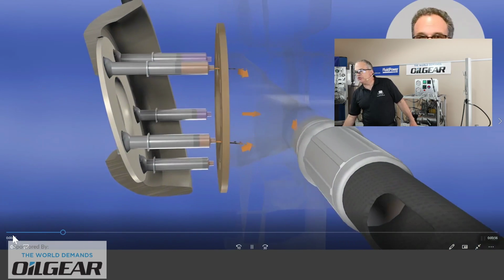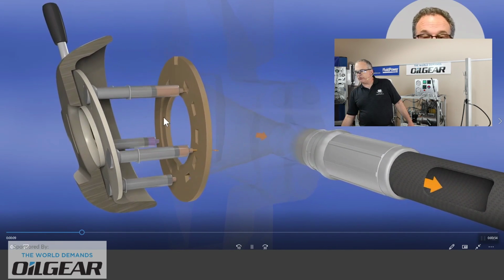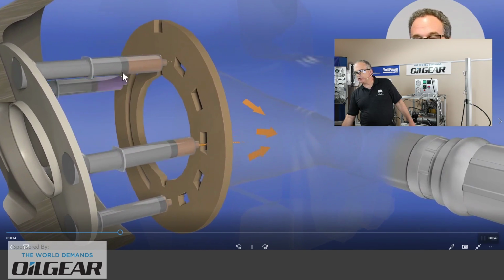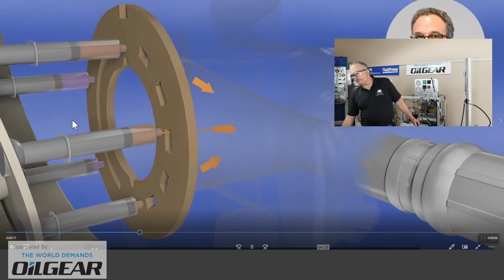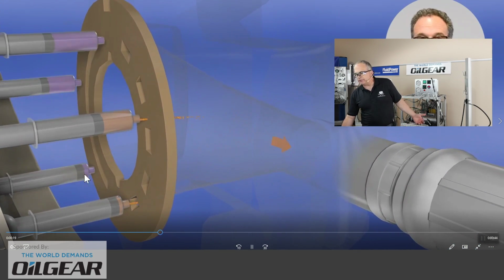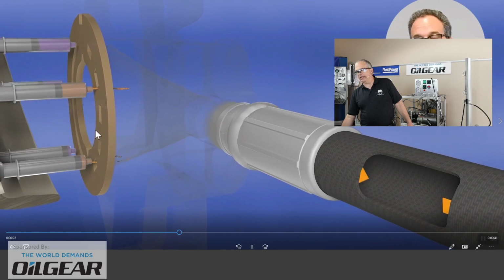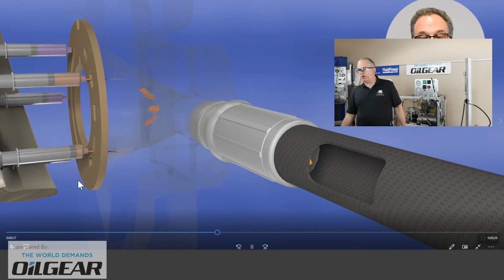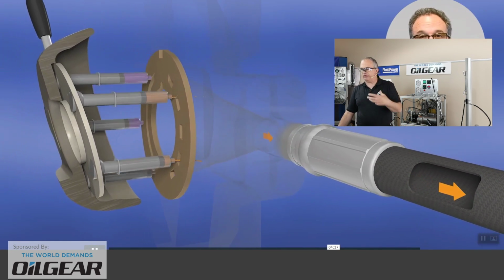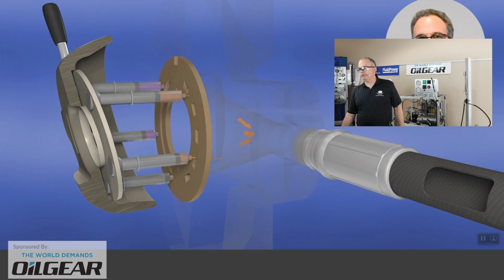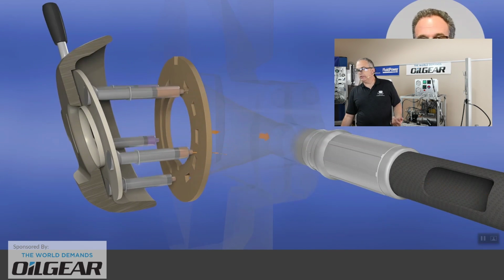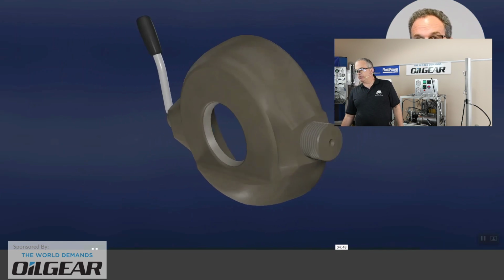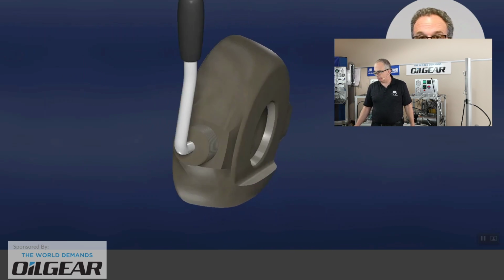And you can see those syringes drawing back on the inlet side, drawing in oil through the larger kidney in the valve plate, sucking in a charge, but then due to the angle of the swash plate, those syringes push forward again and eject hydraulic oil out on the outlet, and hence the need for that angled swash plate, so that we can understand how those syringes, maybe they're pistons actually in reality, draw in a charge of fluid and push back out again and eject fluid. Okay, but really it's not so much about syringes, but let's think about that device called the swash plate.